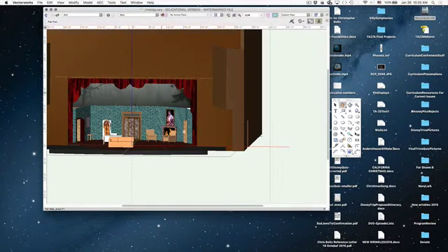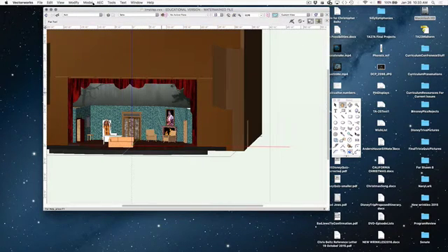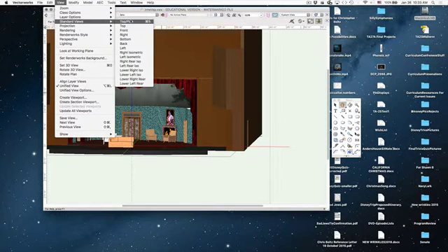Most of the time, we want to get back to our top plan view. That's kind of going to be our home view. You can go to this box up here, okay, and go to top plan. The other thing you can do is go to View, Standard Views, Top Plan, and you'll notice the top plan has a special symbol by it. On the Mac, that is Command 5. I think on a PC it is Control 5, but I don't think it's the Windows key. Really, because Command usually maps to Control. But again, you can check.